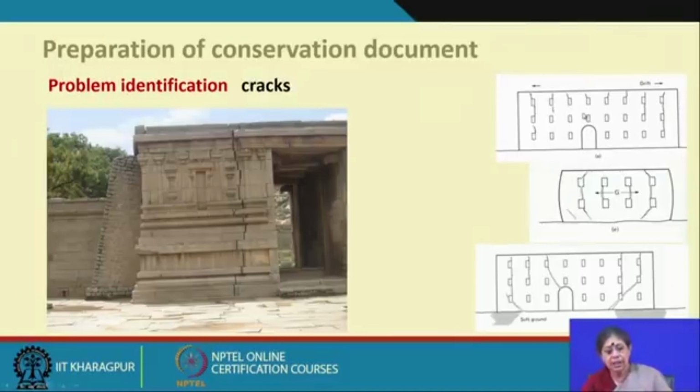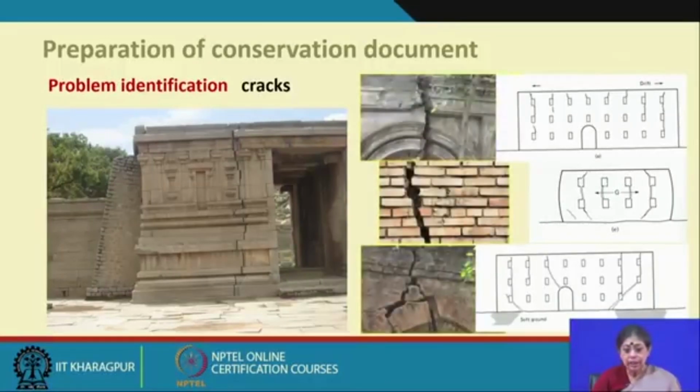Now, these types of cracks are generally due to temperature fluctuations. Now, one can understand what can be the likely cause. So, if required, sometimes the foundation investigation also can be done. And as I say, you can see the severe cracks have developed, which are definitely a structural problem.